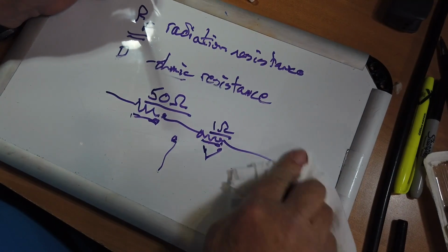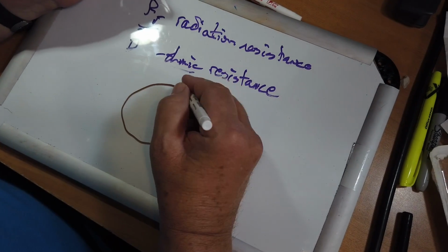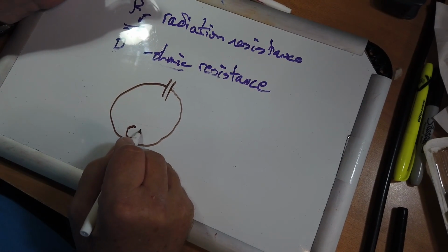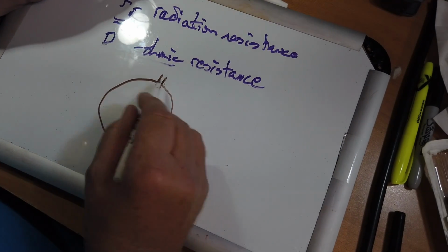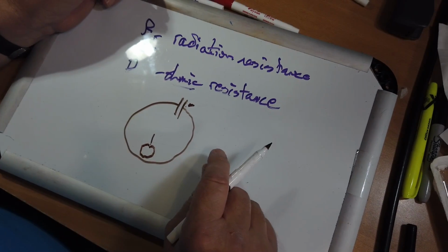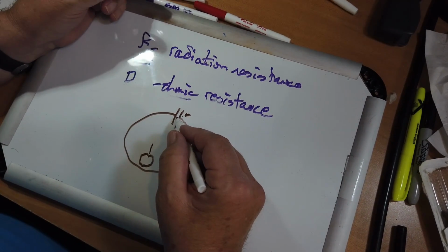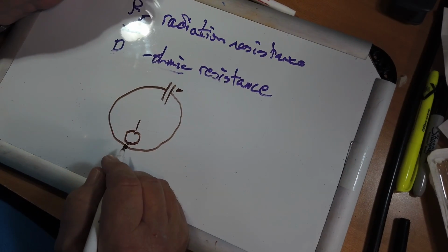Okay? Now let's take a look at your mag loop. The magnetic loop has got a capacitance in here, and it's fed by a small coupling loop, and this is where the coax attaches. Now, you tune the antenna to resonance by tuning that capacitor. And this capacitor has very high voltages across it, low current, almost no current. Down here you have very high current, almost no voltage.